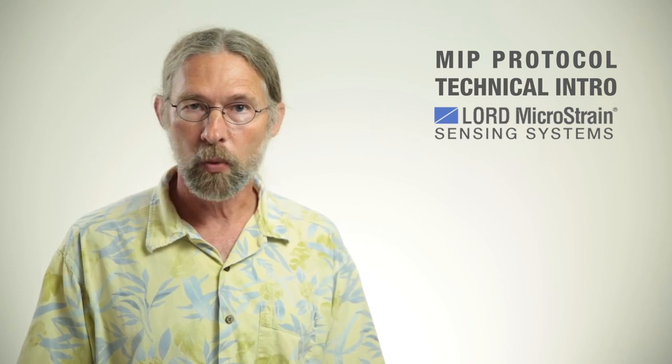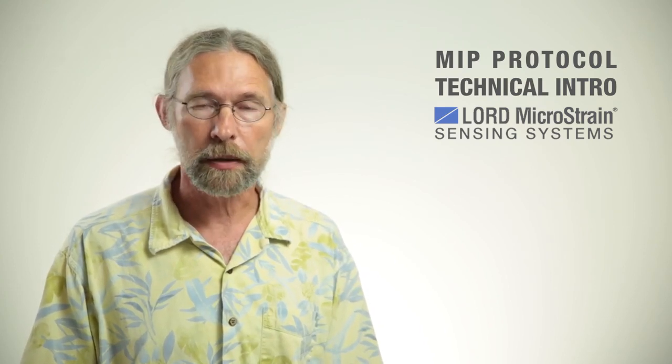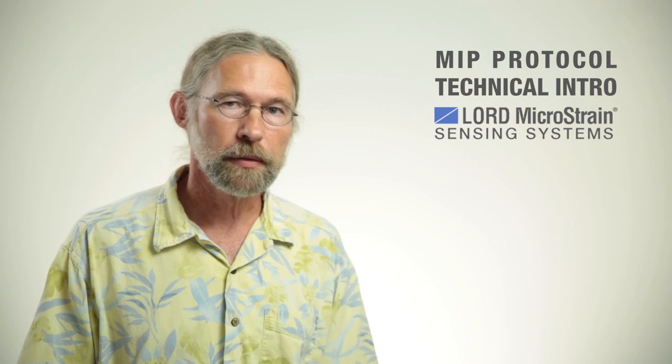A packet only contains fields from one descriptor set. That means when you get one packet, you can examine that 3rd byte in the header and find out what type of data is in that packet, and you can route it efficiently to the code in your microprocessor or your embedded system.